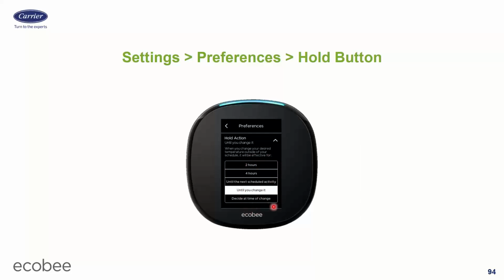Or what I can do, if I don't know what the customer wants, I can pick decide at time of change. And then later on when the customer overrides the stat, every time they override it, it'll ask them, hey, what do you want to do? You want to do this for 2 hours, 4 hours, till the next schedule, or keep it forever? It'll ask them every single time. So for a homeowner, I probably would pick decide at time of change.